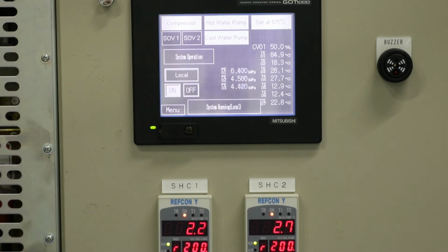And now we will proceed to power on the heat pump itself. As you can see, the heat pump is starting right now, and you can observe the temperatures and pressure on the screen. Take a closer look at the pressures. The first pressure, PE01, is the pressure after the compressor. So the pressure of the gas that is exiting the compressor. You can see right now it's 11.6 megapascals. And the temperature of it is the TE.1, the 001. The first temperature on the right. Right now it's coming up to 90 degrees Celsius.